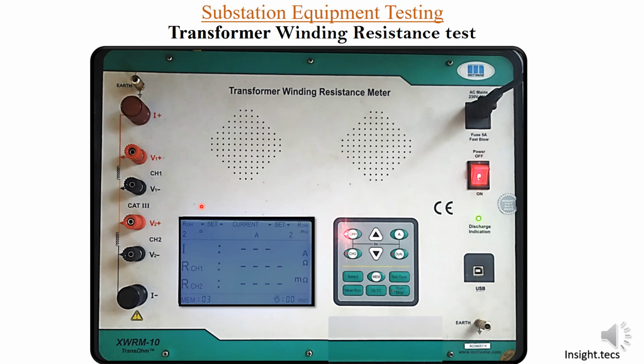Now to operate this kit, you have the provision for earth provided over here. First of all, before using the kit, you always have to connect this kit to the earth. That is for your own safety and also for the safety of the kit. Then it has various channels of operation, as this is channel 1 and channel 2. You can set different amperes and settings for resistance based on which type of winding you are testing.